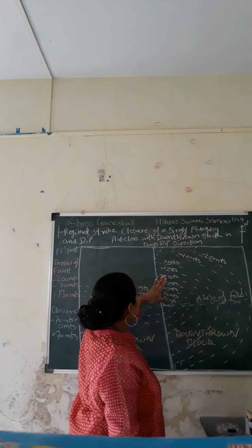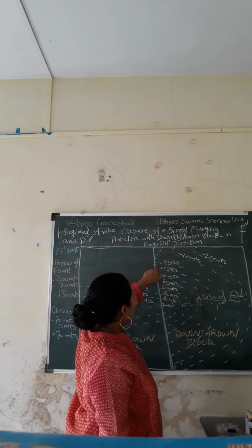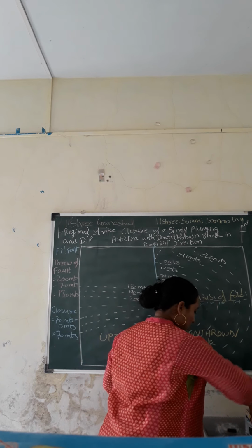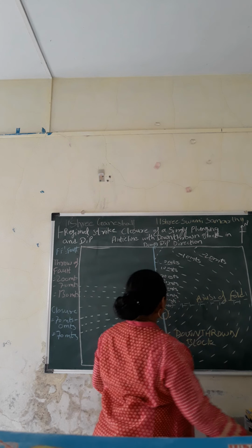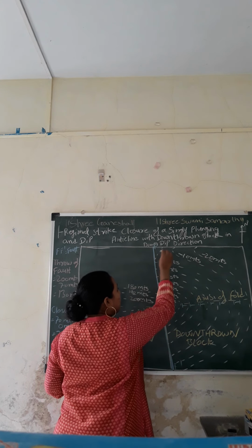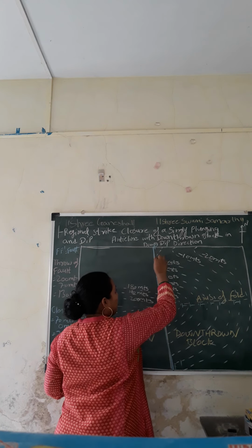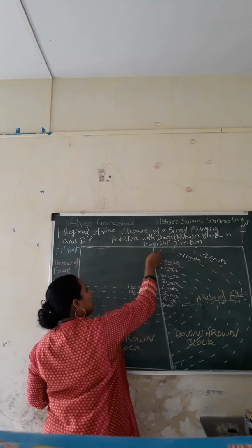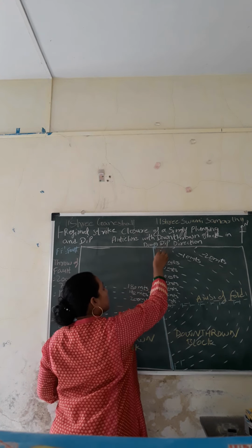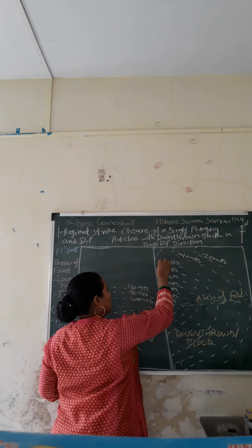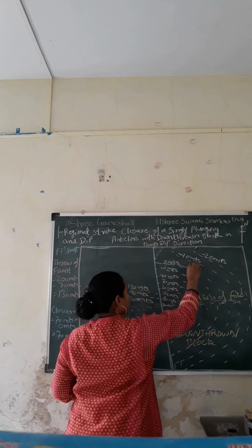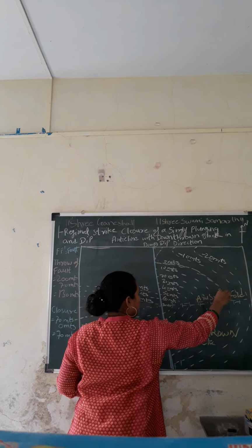So here what is happening is, the lower boundary of the closed area, which we show by green color mostly, will be at what meters? It will be at 0 meters, because at 0 meters itself, you see this contour, it ends. After this there is no contour that is meeting the fold. So the last contour that meets the fold is the 0 meters contour. Thereby we can come to a conclusion that the lower boundary of the closed area is at 0 meters.